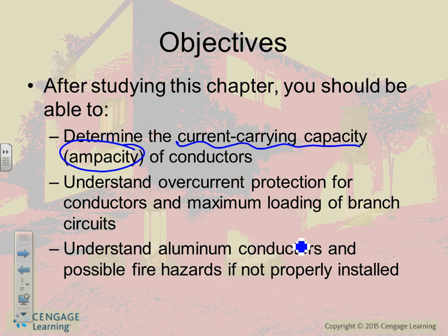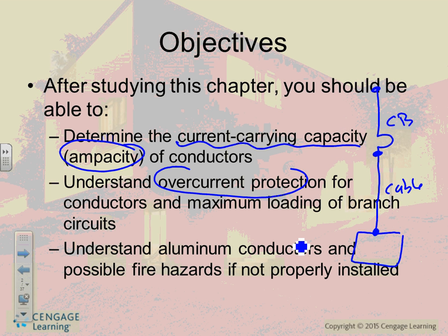Overcurrent protection device and sizing it. I told you guys that whenever you need to pull anything, you always have to start with a circuit breaker, and then you pull with a lug here, tie it. In between them is a cable or conductor, and at the end you have another lug, and you tie to the equipment. That's typically how you pull.